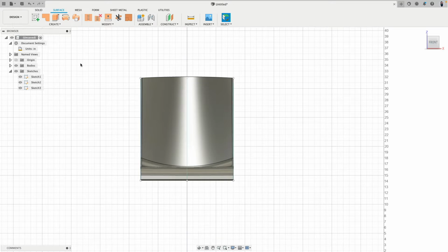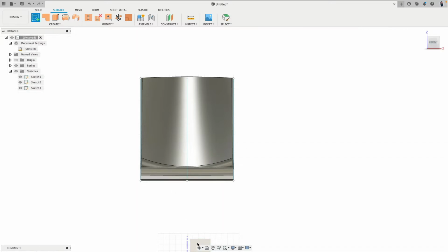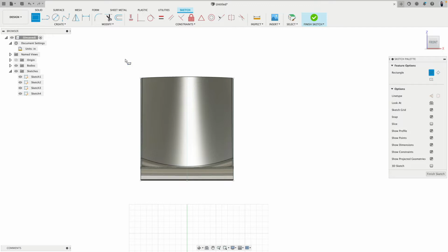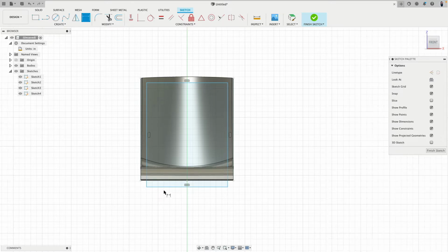So we'll go ahead and create a new sketch. There we are on the front. And then here I will draw a rectangle like this. On top, yes, it goes into the chair on the left and the right side too. And I press D to make a dimension. So this is 14 inches. When later the chair should be 16 left and right, an inch is missing.